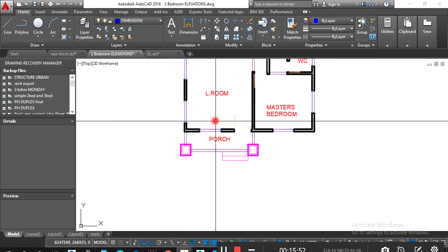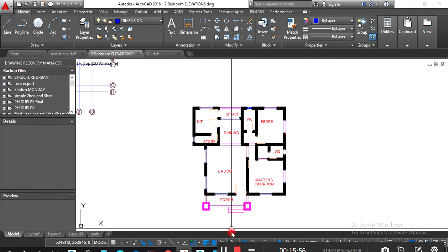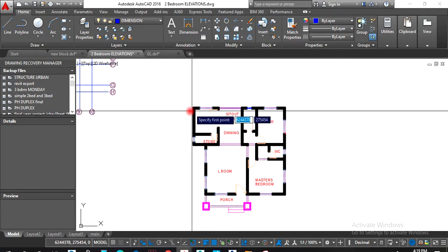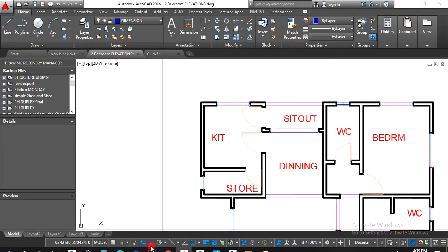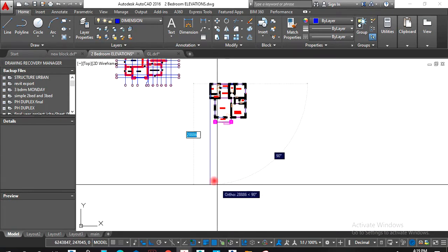When I go click here, I can move them to 40. Fine. Good. So the next thing is to create grid lines. For grid lines, I will left click on line, and with my auto on, that is cursor restriction orthogonally, I'll draw a line here.